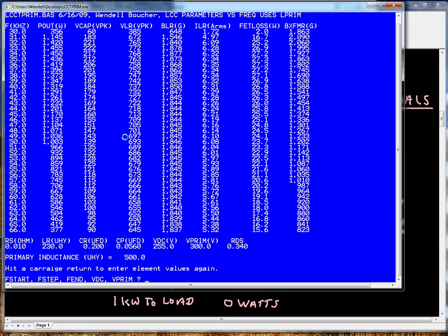This is the voltage across the series inductor, resonant inductor. Again, the peak value. Now this is the flux density if you have 1 centimeter area and 100 turns on the inductor. This means when we're running at this voltage and this power at this point, we have to calculate the losses for 1,846 watts if we had 1 centimeter and 100 turns. Excuse me, a mistake. I just had a verbal typo. This is at Gauss, not watts.